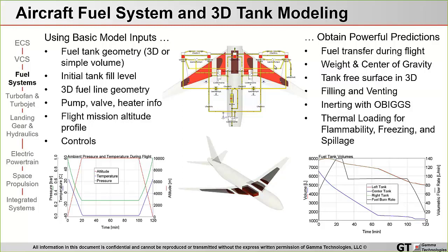That's one of the things that can be studied, but also looking at fuel transfer, weight and CG in a transient fashion, the filling and venting, or if there's inerting of these tanks with OBIGGS phenomenon, the OBIGGS system itself could be studied. And then thermal considerations could also be taken into account, including flammability, freezing, spillage, and so forth.